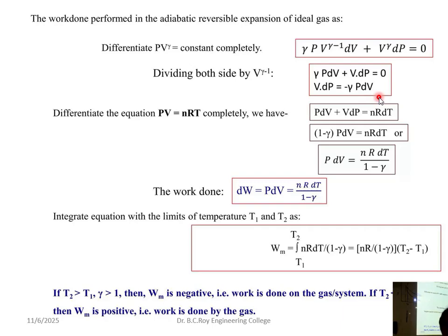Alright. So what is the work done? Here, the area under the PV curve. So for the adiabatic plot, the area under the PV curve will be less, and for the isothermal plot, the area under the PV curve is more. So work done is more. If there is a question, which one is giving more work, adiabatic or isothermal? Obviously isothermal. Achha. Reversible and irreversible, which one gives more work? Reversible. Last year I did the numerical derivation. Some of you are present.